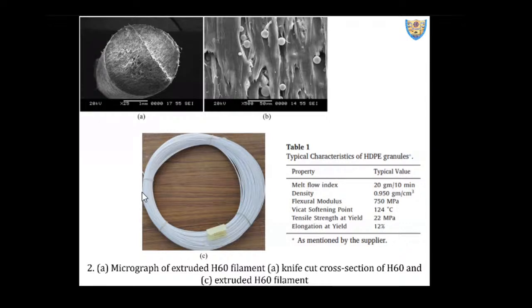So in 2B also, in the micrograph, you can check them. So these are the intact microballoons and uniformly dispersed. And then once we formalize this, the production routine starts. You set the parameters, you extrude the filaments. And that's what I extruded: filament of HDP with 60% of microballoons embedded in them with no fracture or breakage of the microballoons. No doubt there is entrapment of voids because we are using a non-vented type extrusion. So that's how it goes.